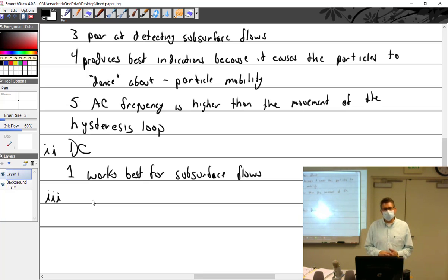Then you cannot do anything that you don't have approval for. So, like in there, I took a little grinding disc and I polished it. That is a 100% illegal move. You can't do that. At the moment in real life that I did that, I'm condemning the crankshaft. You can't remove material from a crankshaft.